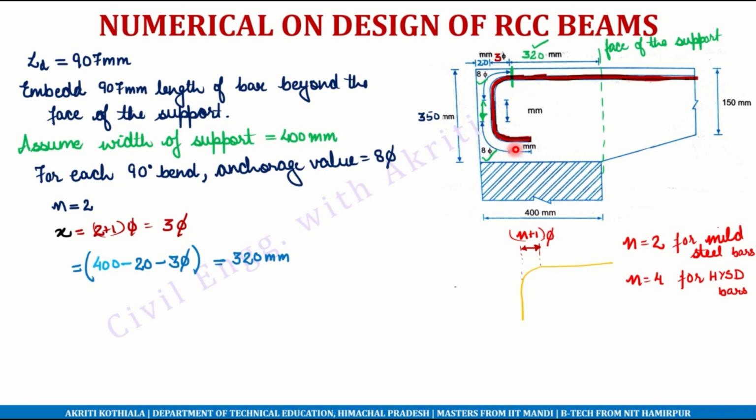Then some distance will be left out for the bending as well. So 85 here, 35 here, 35 here. Approximately, I am assuming that this distance can be taken equal to 100 mm. For my sake, I am assuming this value. If the length is more, then you have to calculate this value further.